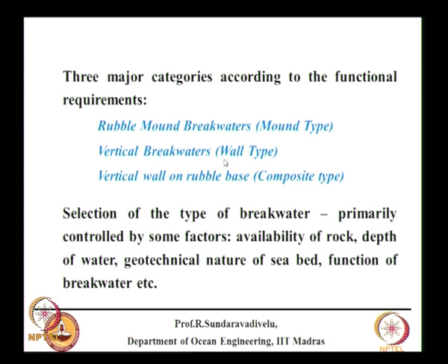In sand, if it is very dense sand, then we can go for vertical breakwater. But if you have a very soft soil, clay or loose sand, then we have to go for rubble mound. But it is not only the soil which is governing, you have the other two parameters also, you have to see it in combination. Even if the soil is rocky, still we may go for rubble mound breakwater because rock is available, depth is less than 15 meters.